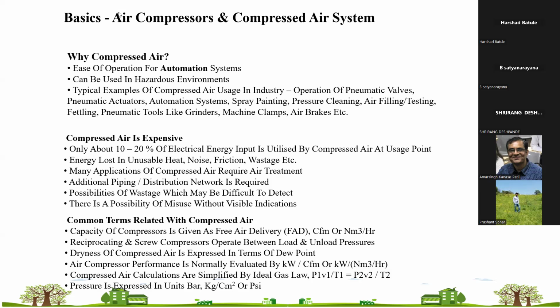Sorry. Whenever we are generating compressed air, there will be a lot of losses. Losses will be in the form of friction, and unusable heat, which is the discharge compressed air, where the work of compression is converted into heat. Another is noise; you'll hear some noise from the compressor. There will be friction in the distribution piping, like in the walls and bends. There will also be wastage in the form of air leakages in the distribution system.